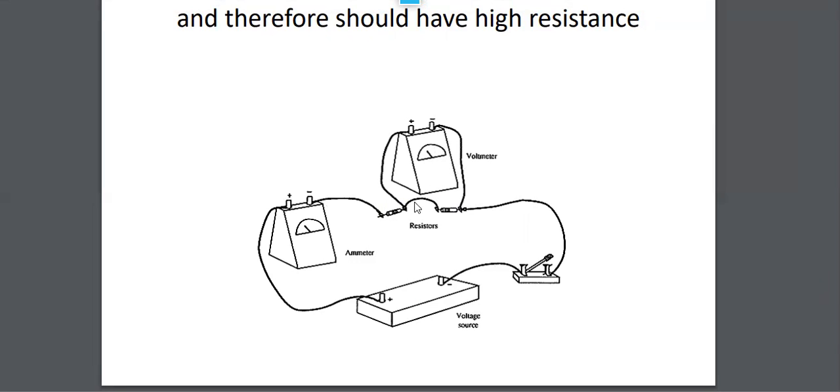This guy over here, right? If you look at how it's wired, there's a lead on this side of this component, and the other lead on this side of this component. So it's measuring across this component here. We want to know, say, what's the voltage drop across this one? And it's part of the total voltage here. The rest of the voltage would drop across here.